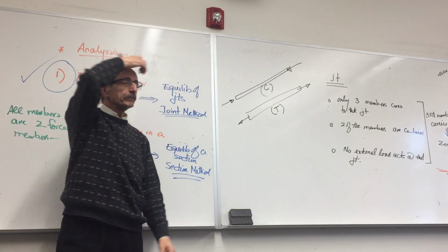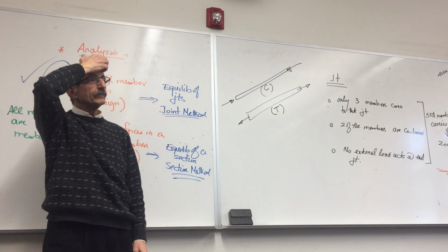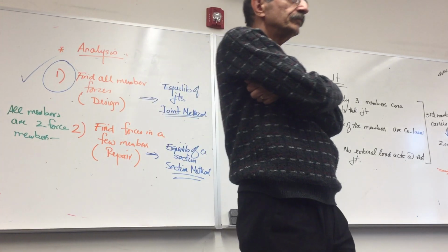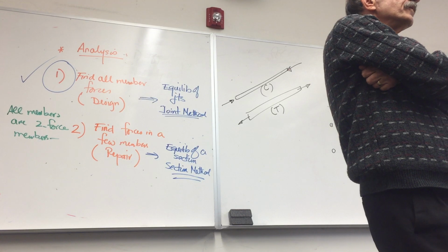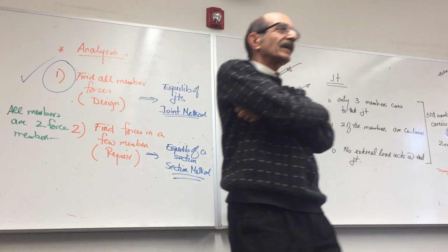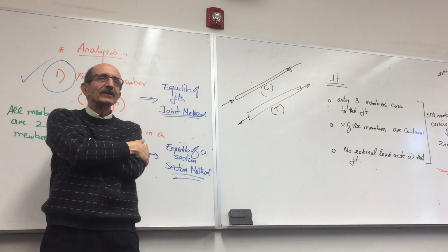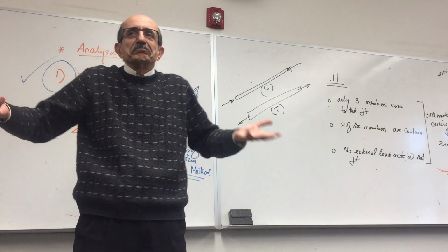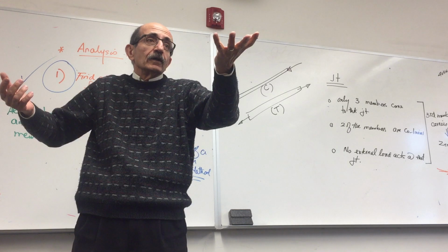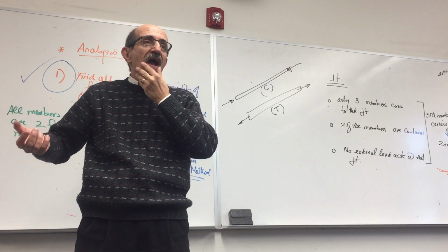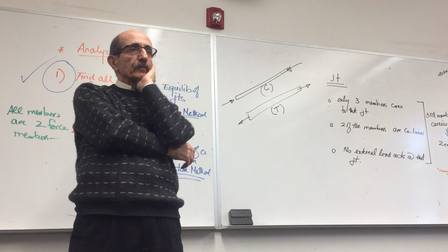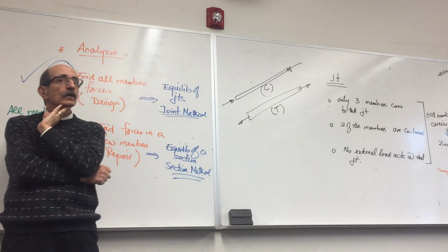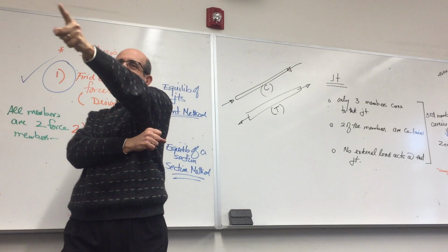So, I'm just a little confused, because for house trusses, in the roofs, they have those. Very good point. That's in fact the question I was going to ask. Okay? So why do we leave those members there? Why do we need those members? Because if they're theoretical pins, then once you remove that member, as soon as you load it the frame would collapse because there's no. No. Okay.